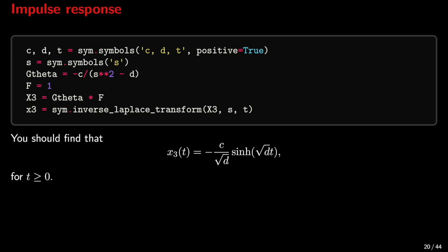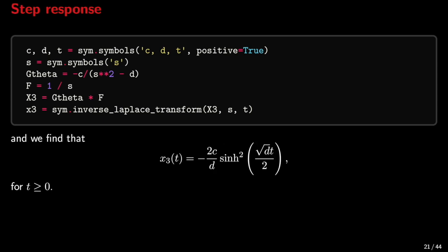Secondly, no friction or energy dissipation has been accounted for when deriving the system equations. We have assumed that any friction is negligible. Again, this is okay if we want to capture the system dynamics in the short term, but not good for long-term predictions. Let us now turn our attention to the step response of the system.